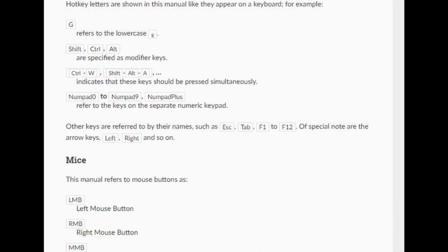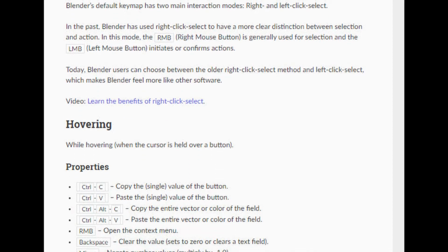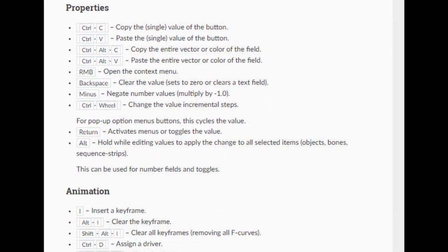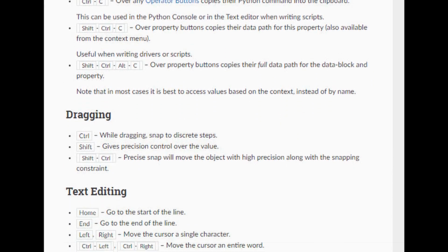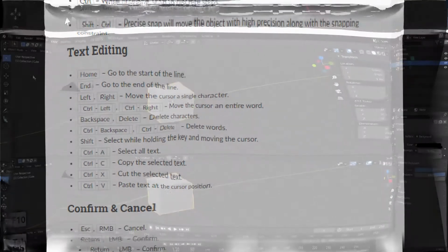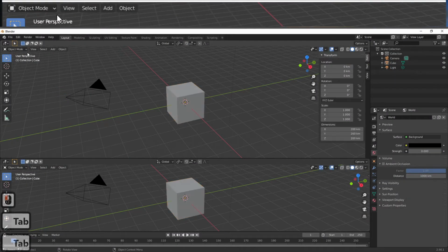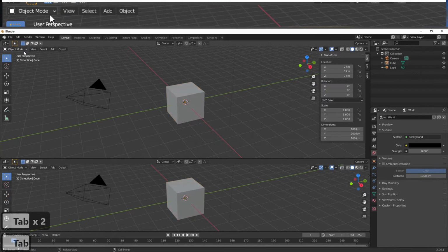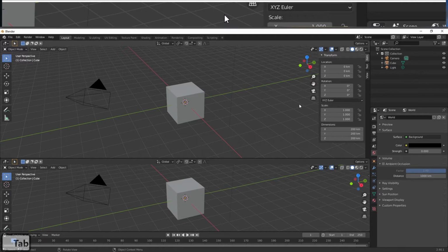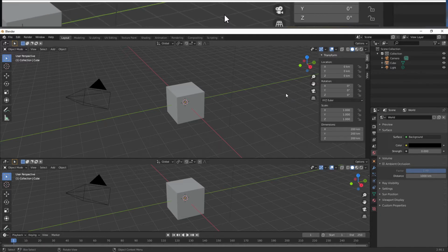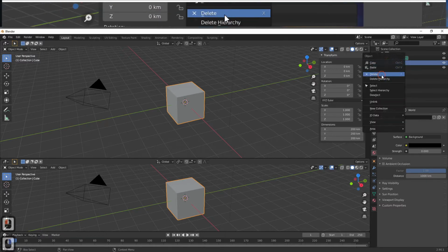If you'll be using Blender a lot, I would suggest learning the hotkeys. It becomes a lot easier, and Blender uses them a lot. Quite often I end up with a different view, as I might have accidentally pressed a key like Tab. So knowing some is useful. Well, Tab is one. It toggles between edit and object view in layout. But for the demonstration, I will try to use the menu as much as possible. So at least you know where those settings are, even if you forget the hotkey.